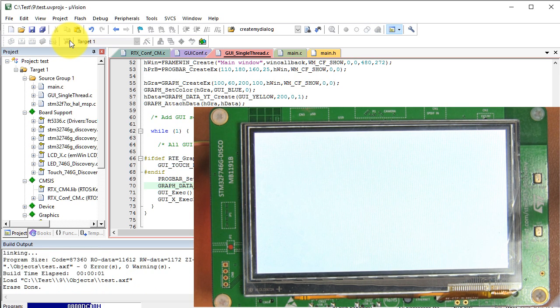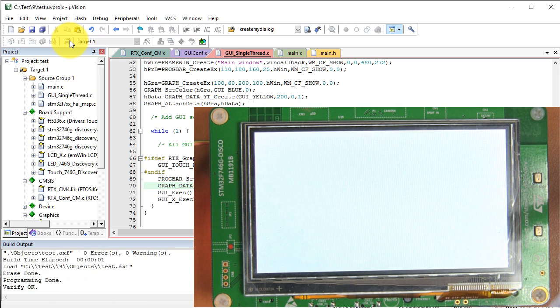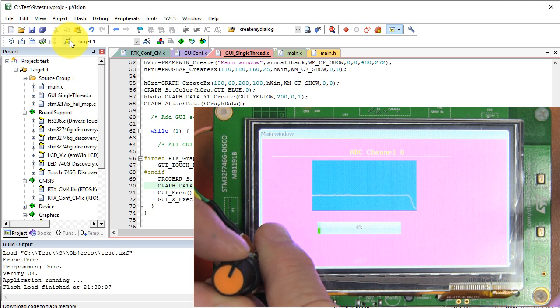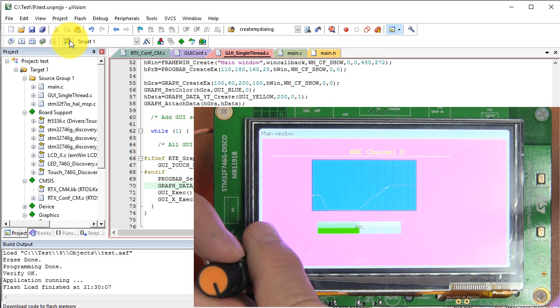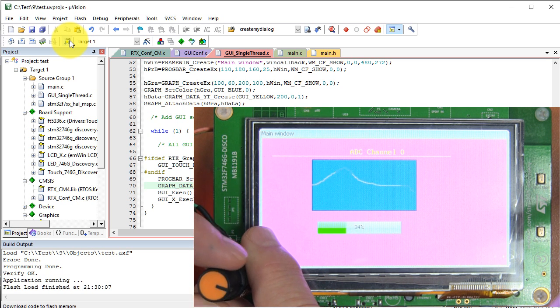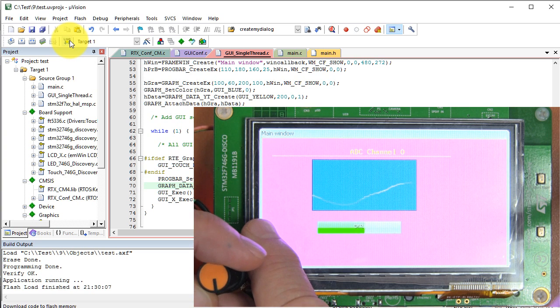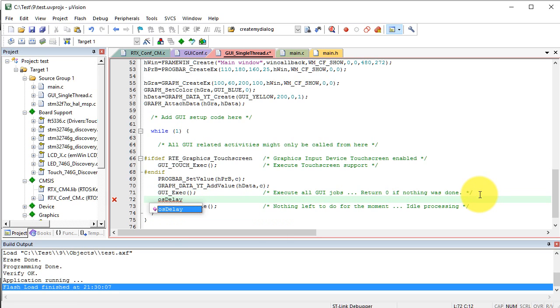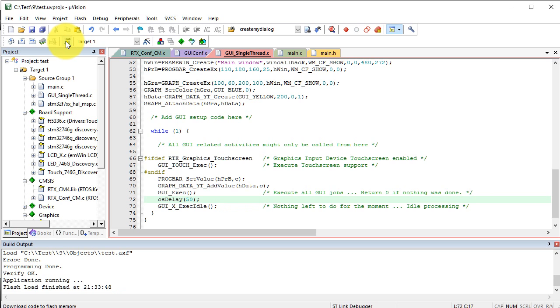We may compile, load, and test the project. We notice that the image is flickering, so we have to use a delay to facilitate the persistence of vision. The speed is now lower, but the visibility improves.